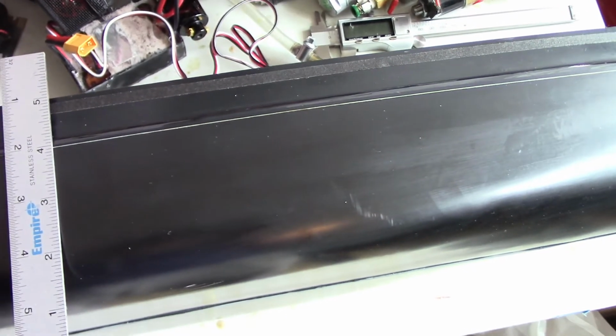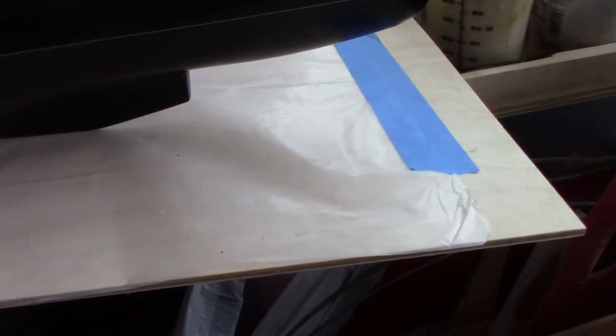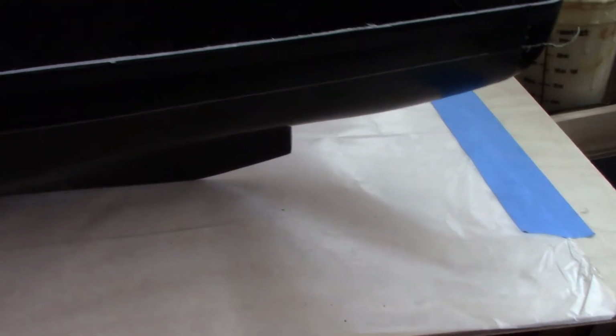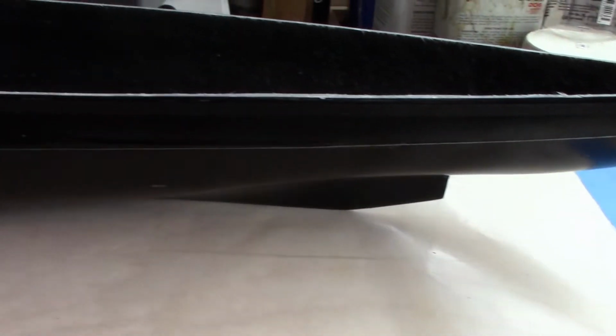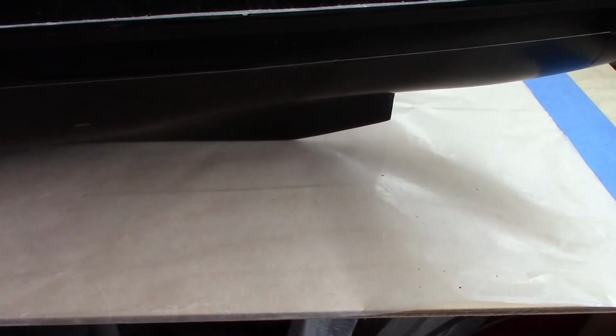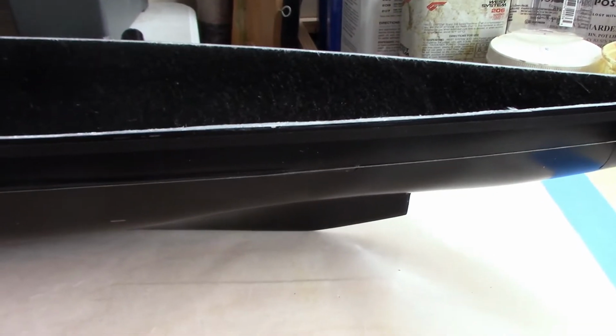So I'm going to mark that out for most of the hull, and then I'll show how I mark the 45-degree turn towards the stern. I'm going to show how to cut the 45-degree, because in the stern area of most boats, the way the hull curves in, they usually curve in before you get to 1 inch below the water line. So the rule says, either 1 inch below the water line or the 45-degree turn.